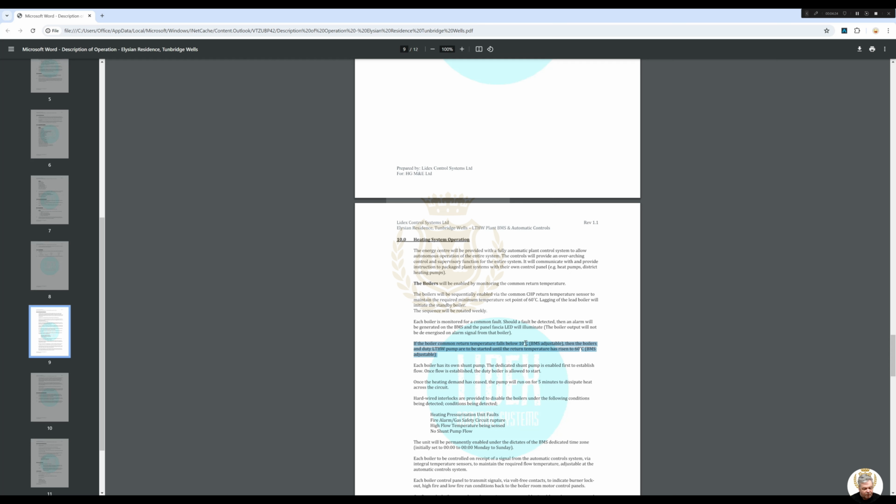Well, it's only going to fall below 10 because 10 is a very low number. Even standing water is not going to be 10 in an LTHW pipework. Standing water is going to be 17, 18 degrees. So I think that line is a bit rubbish, because if it's below 10 then you've got no boilers, end of story, or you've got no circulation pumps, and I don't think the water in the pipework will ever get below 10.